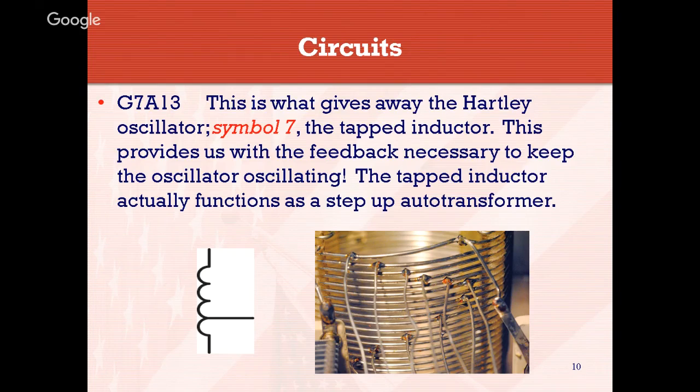Now, you'll also see this type of tapping inside of an antenna tuner. Some of your MFJ antenna tuners, instead of having smooth roller inductors and capacitors that are just variably tuned, will actually have switched number indicators on the front panel. And what those are doing is switching these particular wires in and out at particular points along that coil.